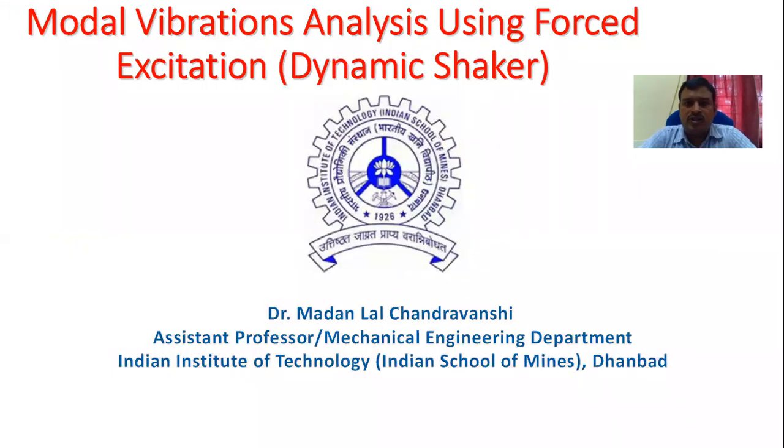Hello everyone. Today we analyze modal vibration analysis using force excitation, or experimental modal analysis using a dynamic shaker. This type of analysis is conducted when the structure is big enough that it is not possible to excite it with an impact hammer. For that purpose we excite it with a dynamic shaker. Now let's see how exactly the setup has to be made.